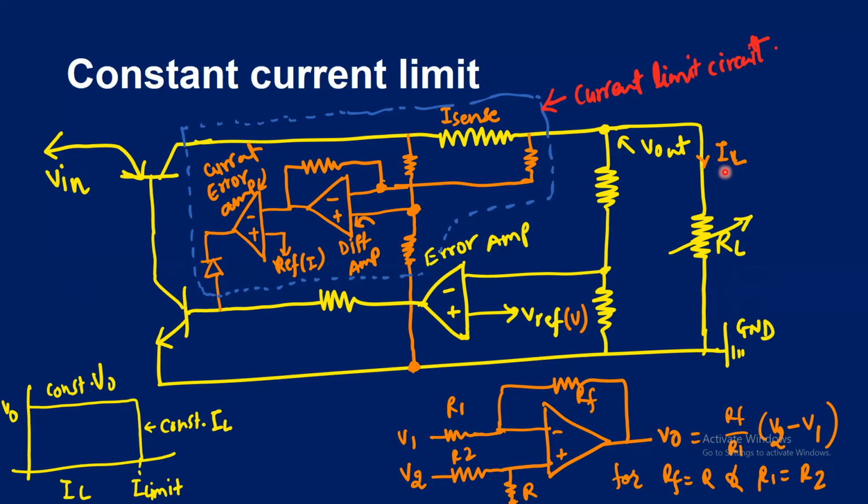For example, if a specific regulator IC is guaranteed to source a load current of at least 250 milliamperes without going into current limiting, you don't activate the current limiting as long as you operate the IC within the specified value of maximum load current, and you also save the extra power dissipation in the circuit.